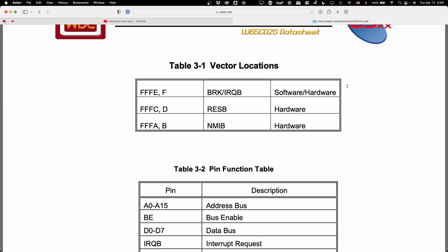Yeah, and with the 6502, we don't have that ability. No. All that you can do with the interrupt vector is know that an interrupt has occurred. And then within the interrupt handler, completely in software, or almost completely in software, you have to figure out who triggered the interrupt.